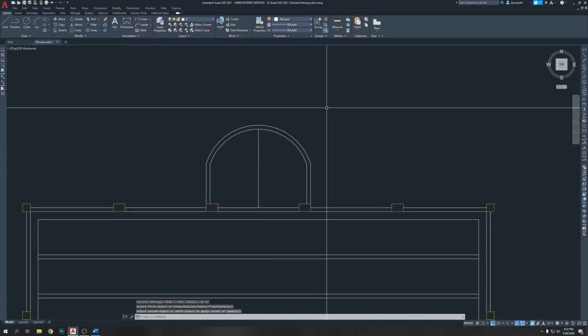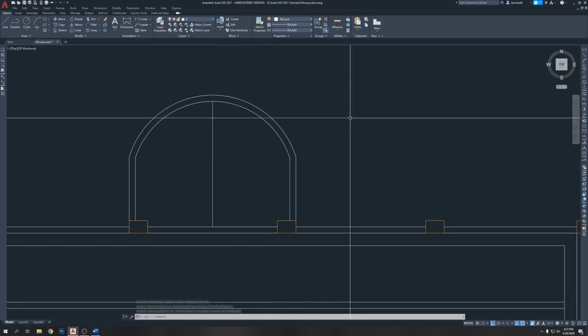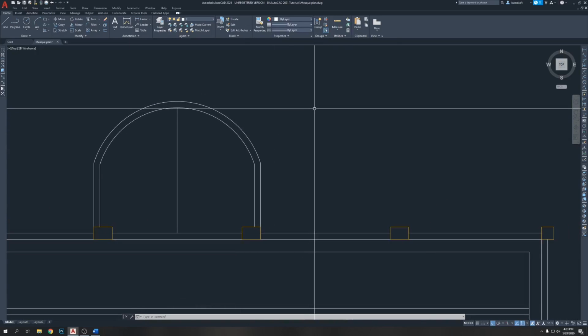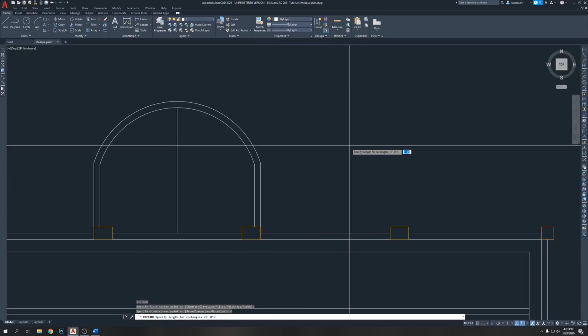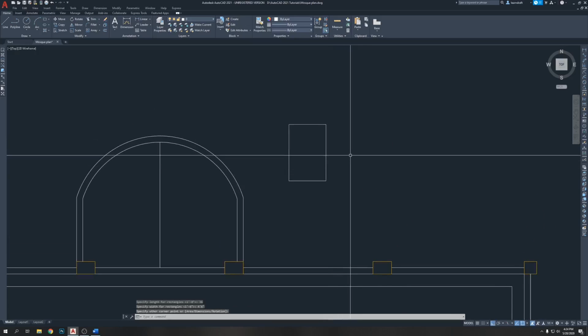and we're good. So now we're going to draw a musalla for the Imam. So we're going to see how much space is left. REC, enter, click, D, enter. Most musallas are like 1 foot to 3 feet, so 36, enter, or let's say 4 feet 6 inches, which is 54. So I'm going to go with 4 feet 6 inches, enter, click.